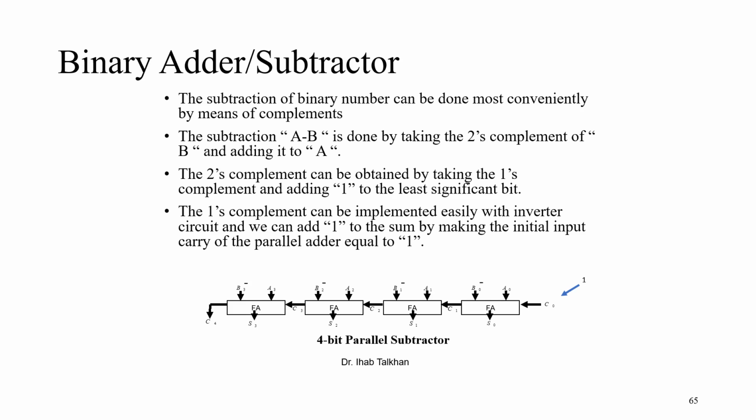If I do that, you will end up exchanging the whole operation from full addition into full subtraction. So if I change C0 to 1 and I change every B to B bar, I end up using the rule of the complement, ending with subtraction instead of addition.